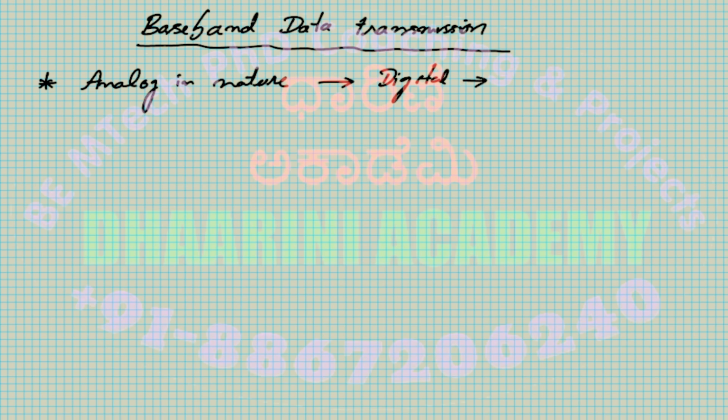So what you are trying to do here is that both the y and x axis get quantized. In the sense, you cannot have any value you want. You will predefine, like, okay, after 0, I have 1, then 2, then 3. It's not necessary to have values like 0, 0.5, 1, 1.5. You quantize. Okay, this is the fundamental meaning of converting analog into digital.